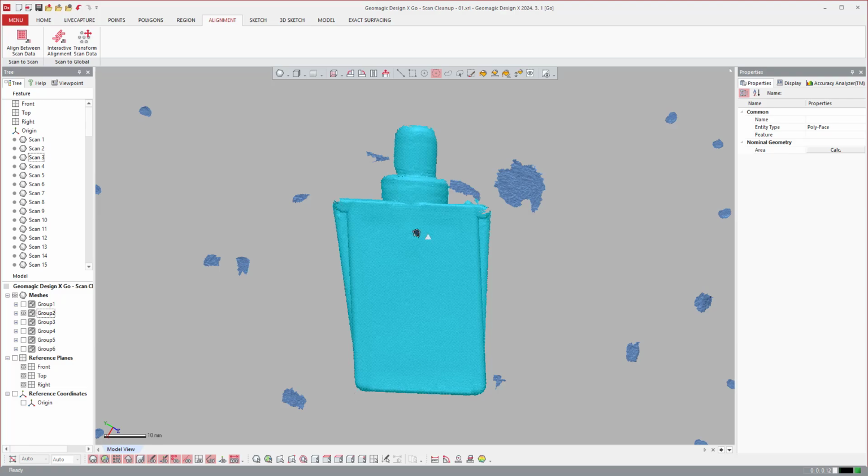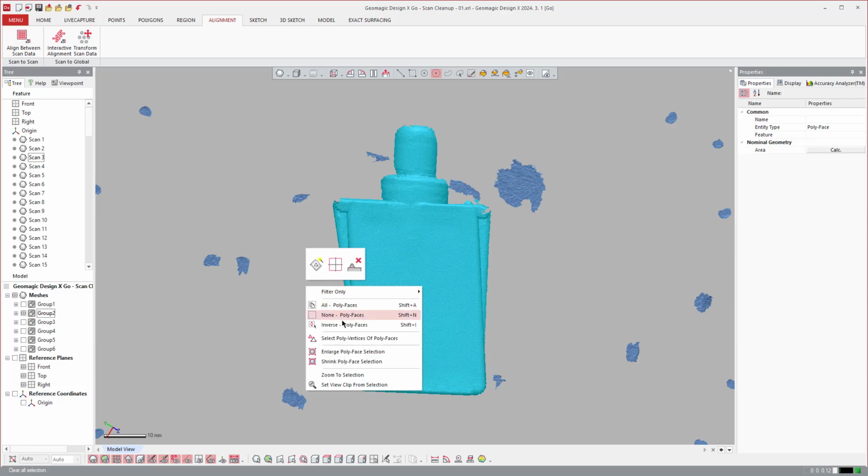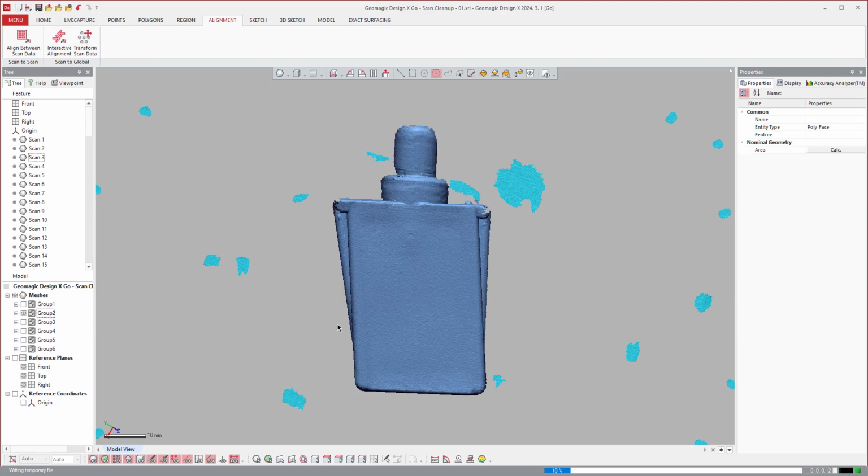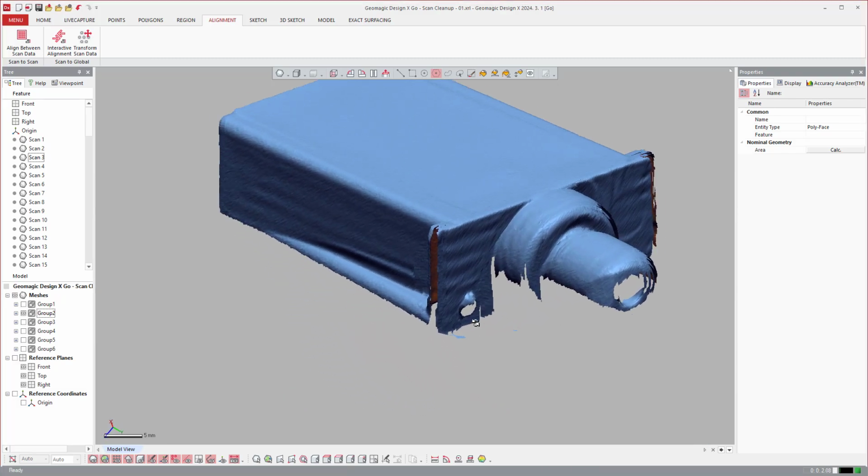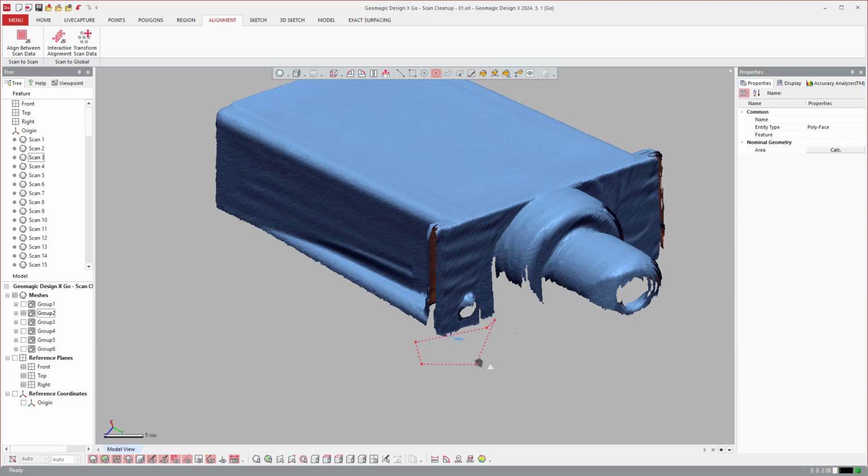And I right click and it will select it there. And then I can say inverse, delete, and go from there. So that was the second option, we went ahead and used the polygon tool. And then I'll usually look at it from different perspectives. And you see here, holding shift will allow me to add that part to that part and then hit delete.